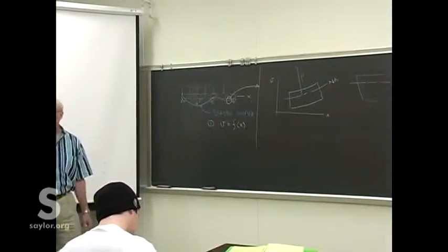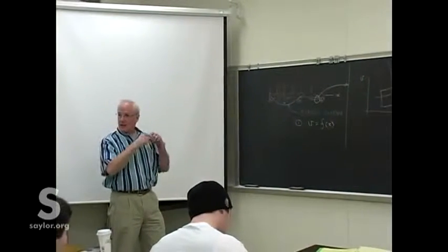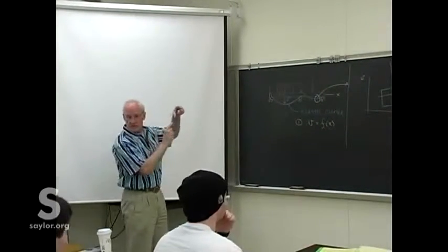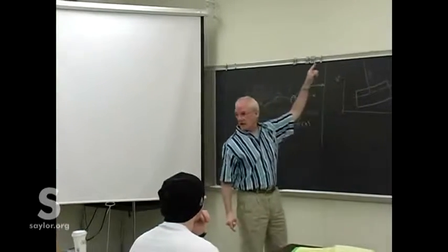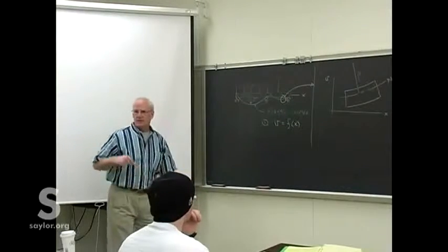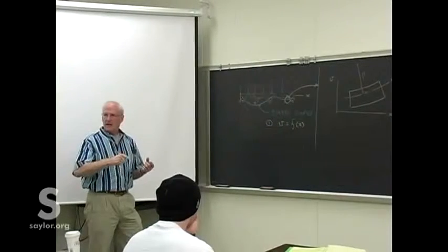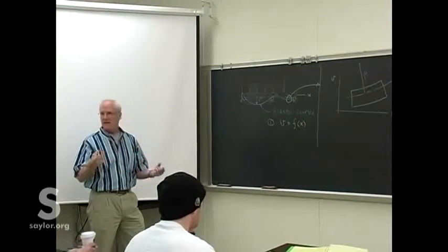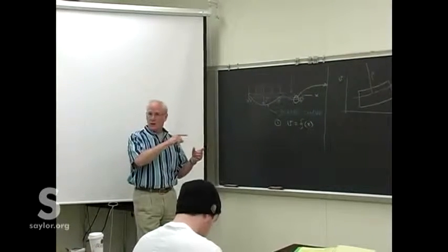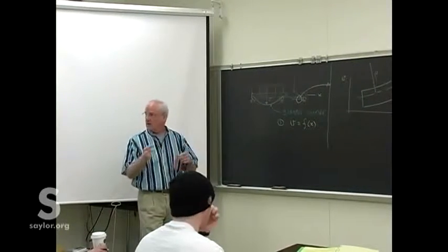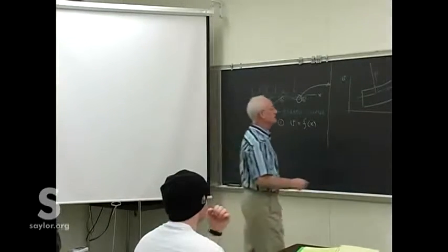In fact, there will be places where, because of the loading and the constraints, the beam actually has no curvature. It may have some slope, but it doesn't have any curvature, so the curvature is actually infinite at those places. And start bringing back in your calculus as you start thinking of the functions you looked at. The second derivative especially told you what the curvature was, and how did you find where you went from one type of curvature to another? What happened? All those types of spots are going to be of some concern to us today.